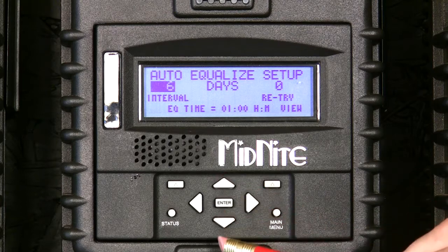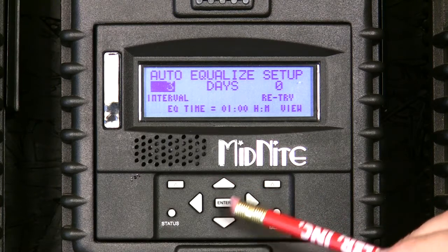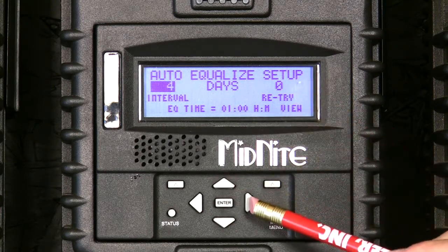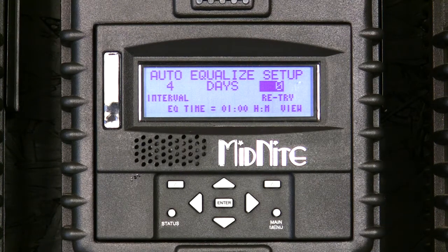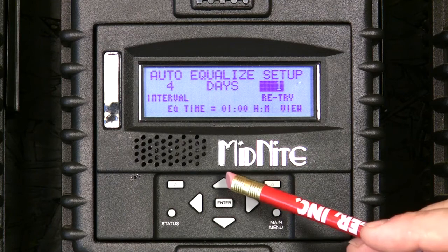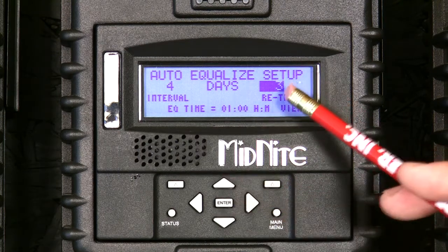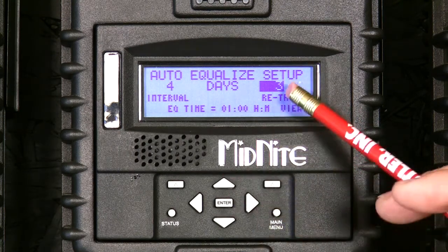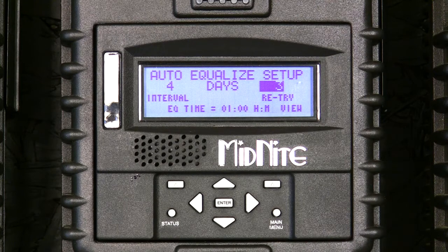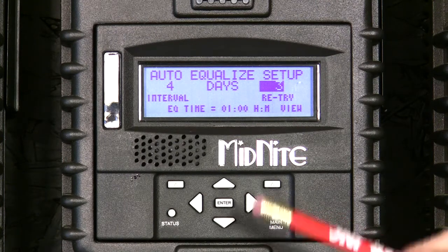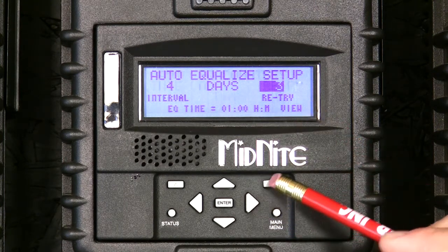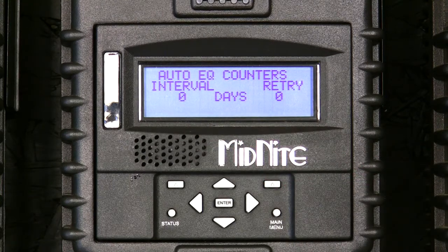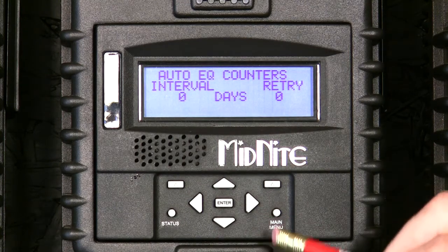This is the days between equalization charges. This number over here is the days it will try to equalize. So if it does not accomplish it on the first day, it will try again, and again, depending on the programming we have there. When it reaches the limit of that, it will drop out and go back to its original charging algorithm. We have a view button where we can see the interval, counting up to the next charge stage. In this case, we just set it, so there are no values there.